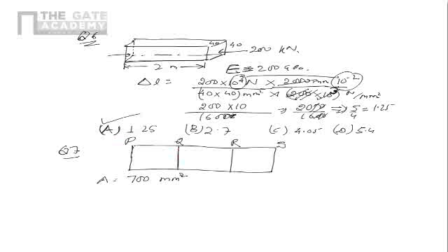At the end P, we have a tensile force of 63 kilonewton. At Q, we have, let's say, a left acting force of 63 at P, a right acting force of 35 kilonewton at Q, then again a right acting force of 49 kilonewton at R, and a compression or left acting force of 21 kilonewton at S. We are supposed to figure out the value of stress in the QR segment. So in this central segment, what is the stress is what we are supposed to figure out.